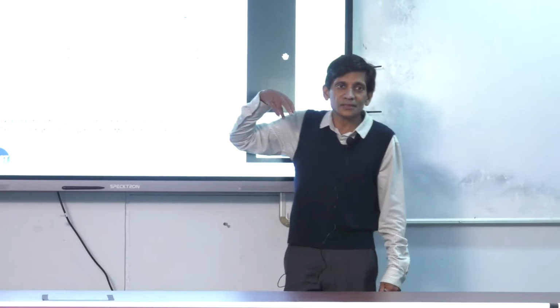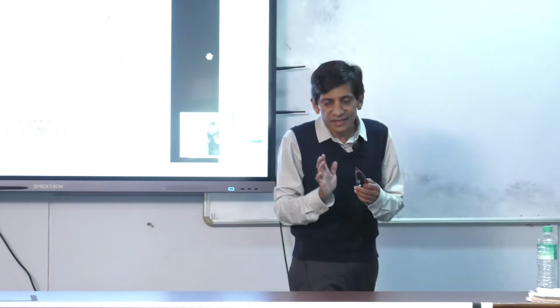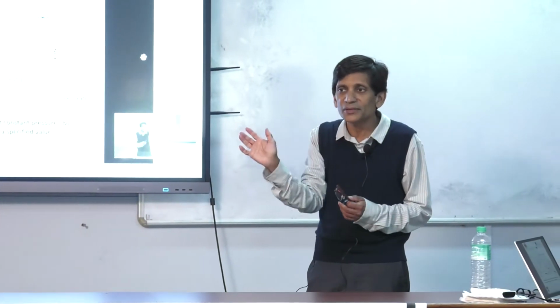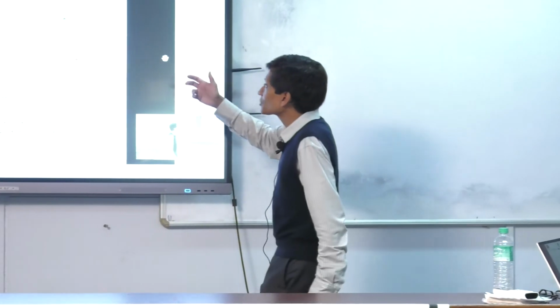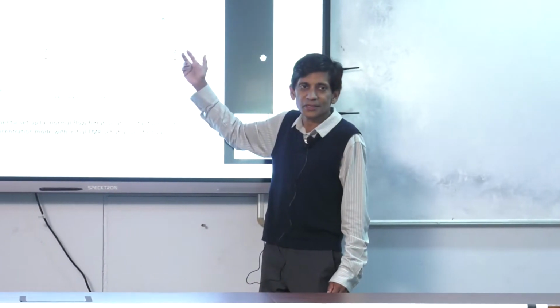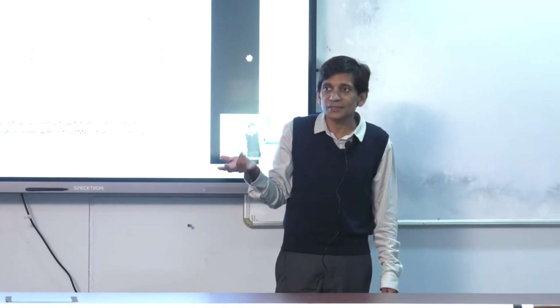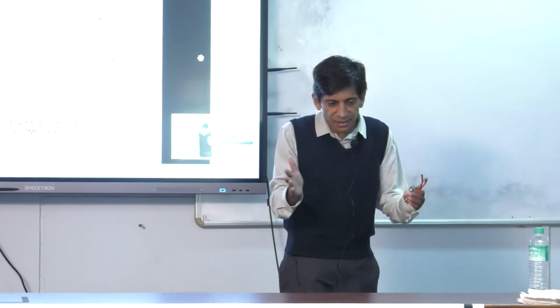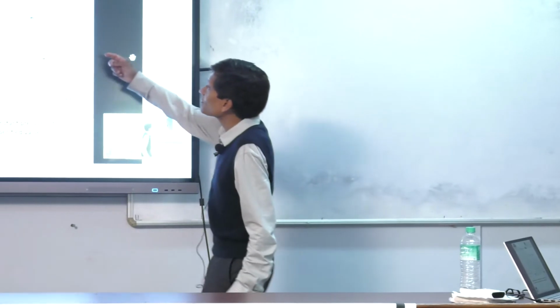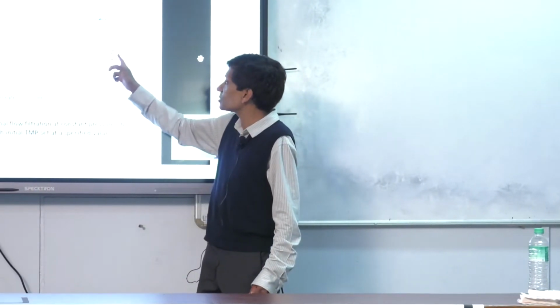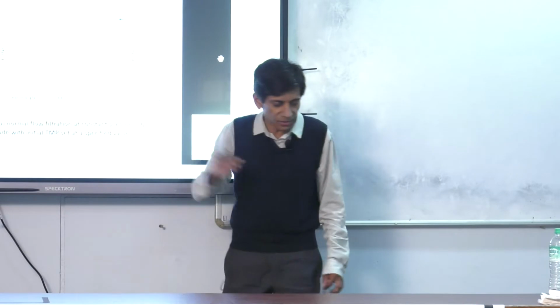And actually, the way one works out how much fluid goes one way or the other is that the resistances have to be matched, okay? So the amount of flow that goes that way relative to this way just depends on the relative resistances, okay? It's like in electric circuits, right? You have two resistances and you have a bifurcation, and so the amount of current that flows one way or the other will depend on the resistances. So all we are doing then is artificially changing the resistance through this way so we can flow more this way, okay? That was the purpose of these experiments, okay? All right.